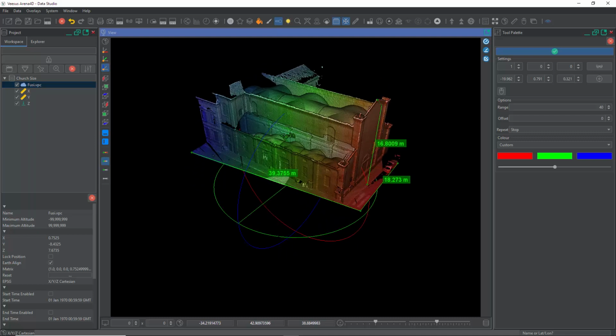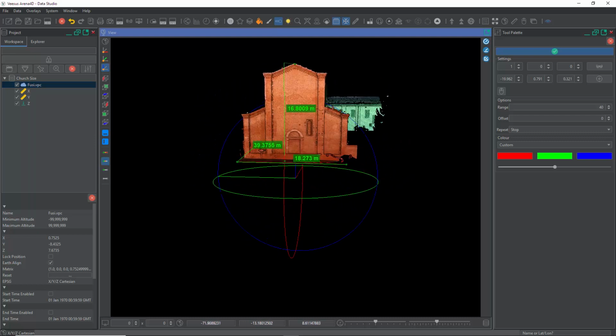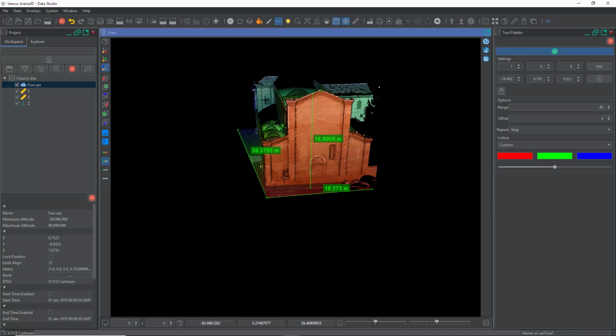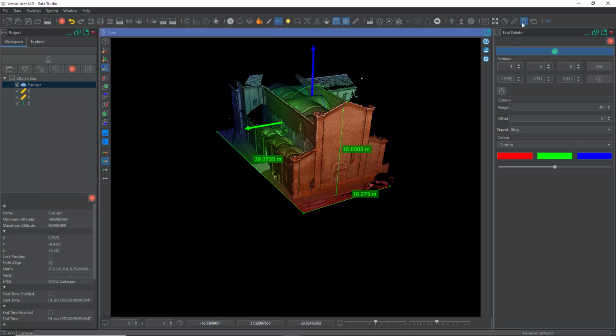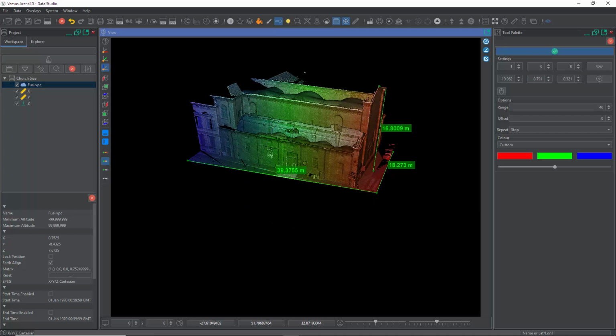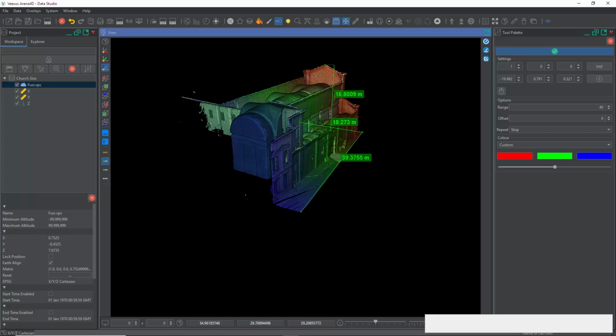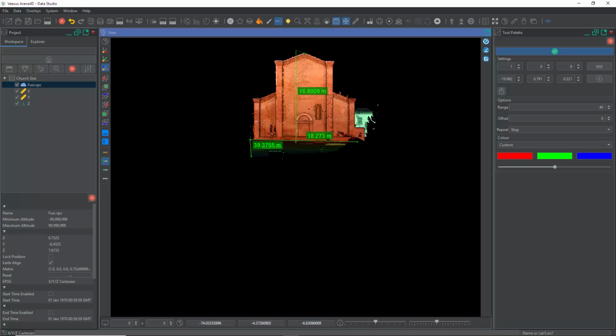If your point cloud data isn't as well aligned, so squared up, and you don't wish to perform rotations and stuff on the point cloud data for other reasons, then say if I want to do vertical here, I can position myself on the side of the data. So I'm positioned down the side. I'm just going to click direction.